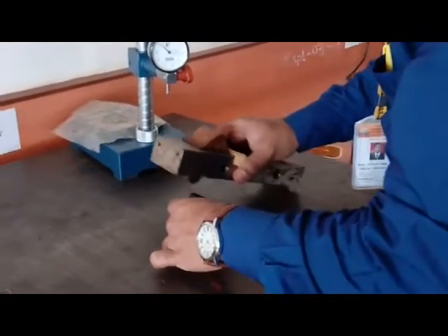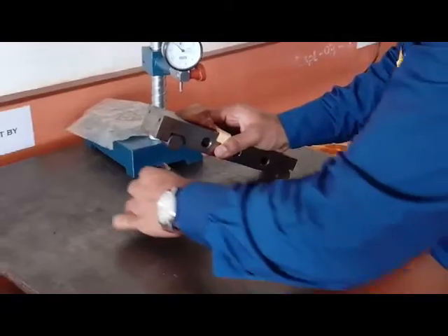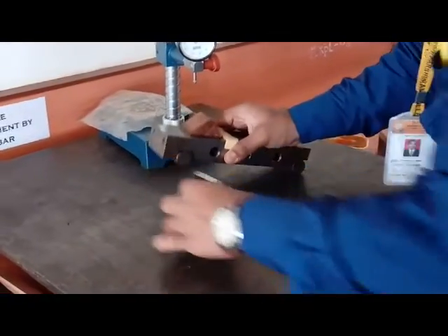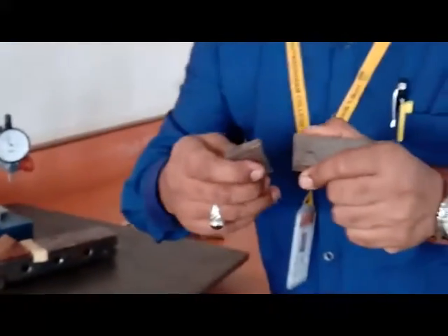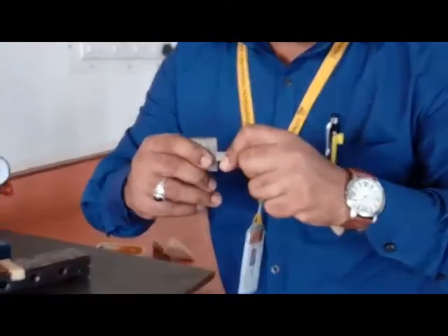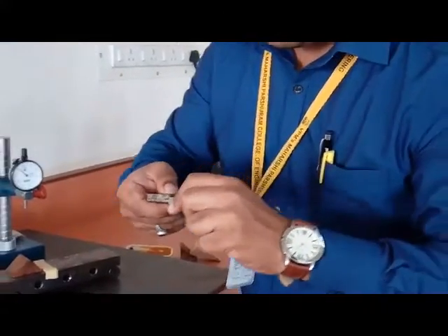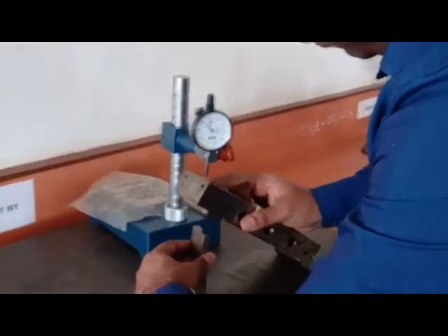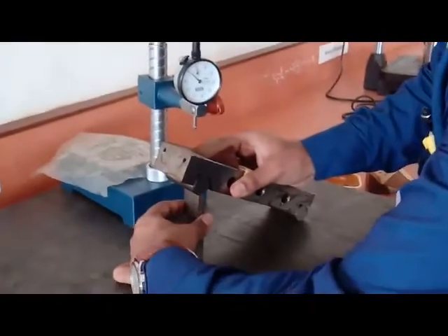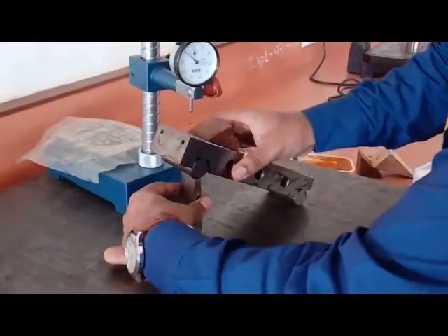Then next we will add slip gauges one by one, but for adding we will use a specific combination. The ringing of slip gauges is done by this technique, and over here we will check whether the system is accepting the height or not.